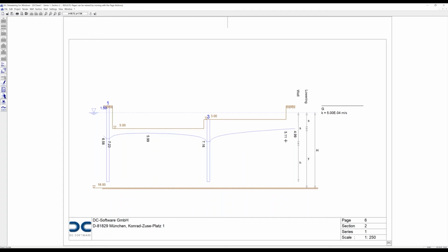We don't go to the 5 meters and 50 that we had before. So the 3 wells at this deeper foundation pit are sufficient for the less deep one. So we don't need extra wells for this second part of the foundation pit. So at any point, we have a sufficient depth compared with the depth of the foundation pit.